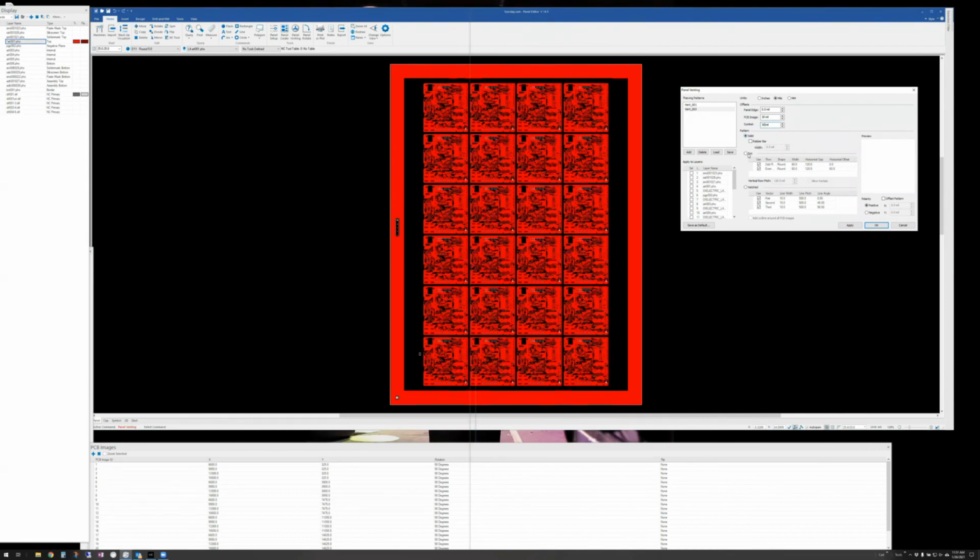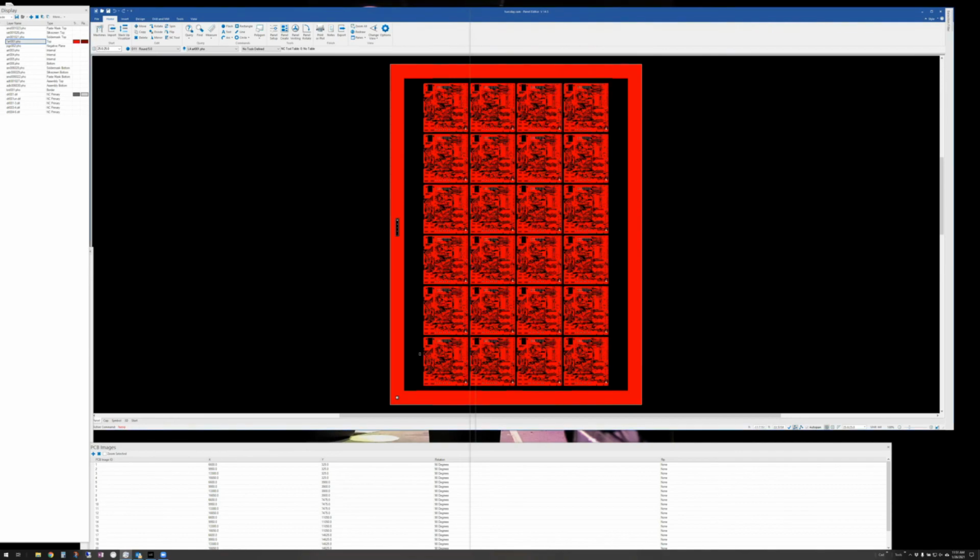And it's going to be a dot pattern, and I can create the dot pattern however I want to here. You can save these and recreate and import them, the dot patterns, but I'm going to use this one, and then I pick the layers that I want it to go on. Let's just put it on this layer here and hit OK, and I think it did that.